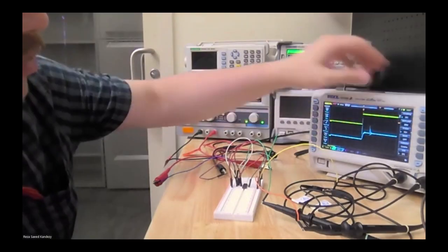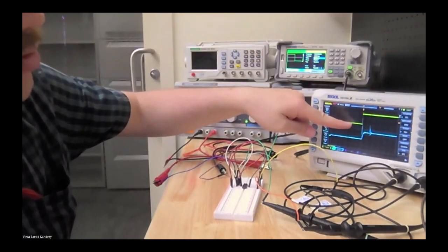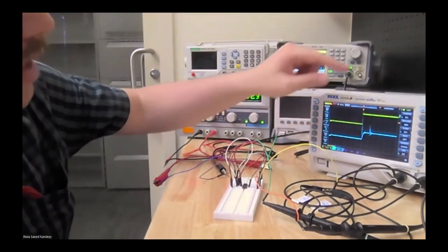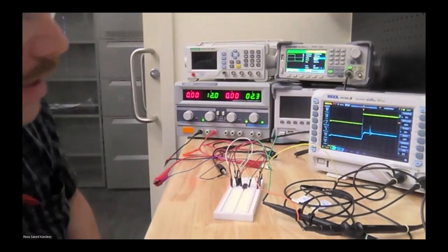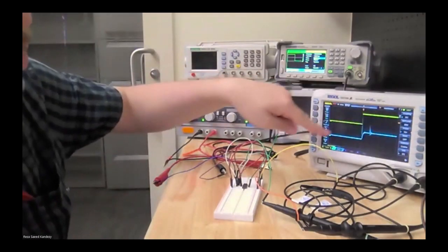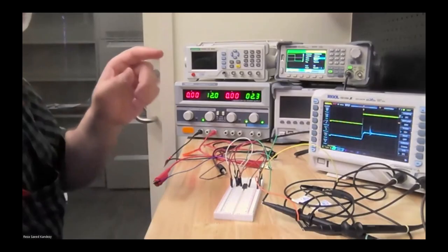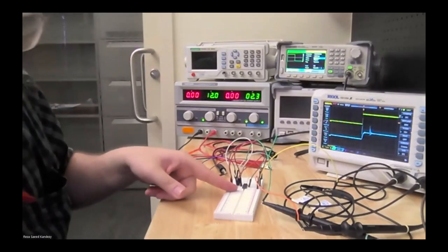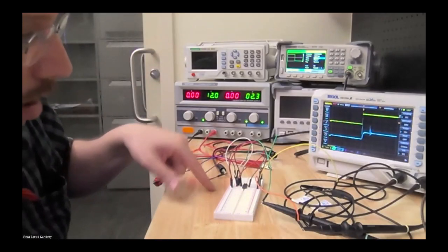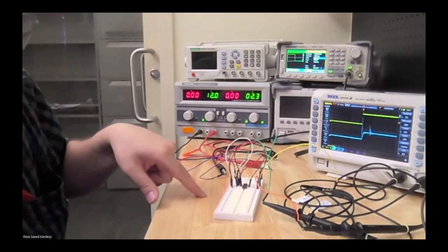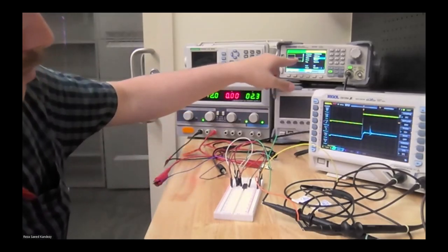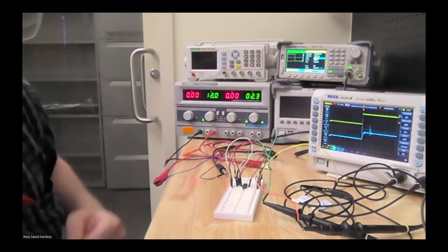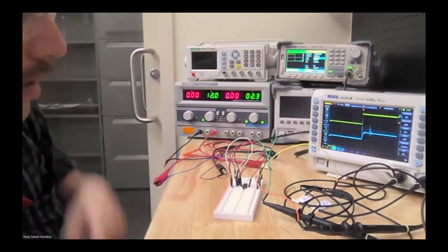And I applied that, and I'm using the oscilloscope. Channel 1 detects the input, which, as you can see, is a square wave, and I zoomed in for calculating the slew rate. And channel 2 is the output. As we said, this is a unity gain buffer, so you have to short circuit the output and the inverting input, and use the non-inverting one to inject the signal to the op amp.